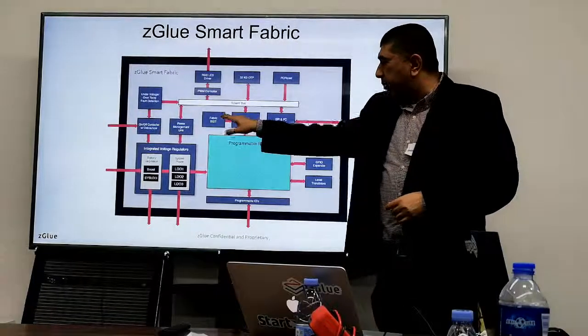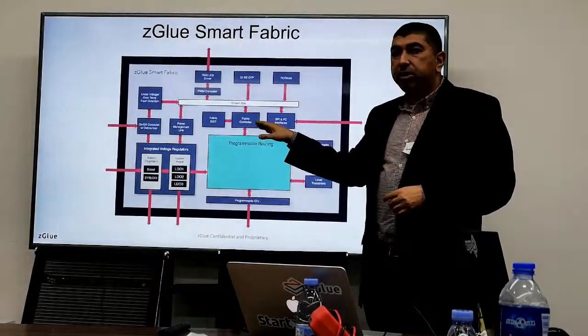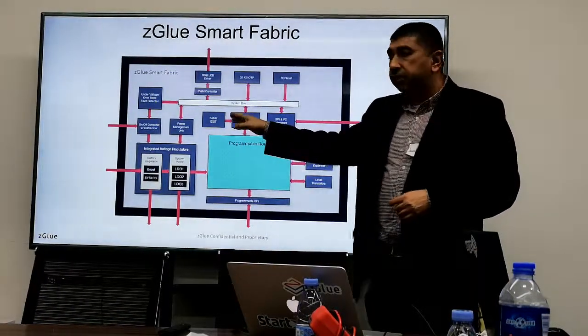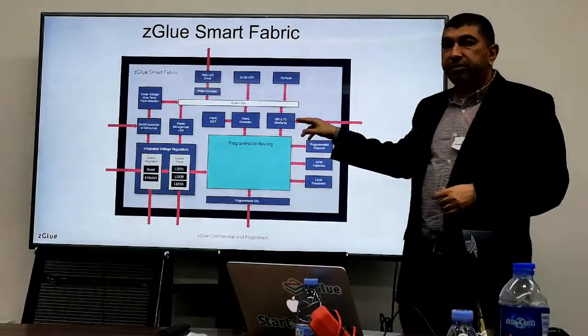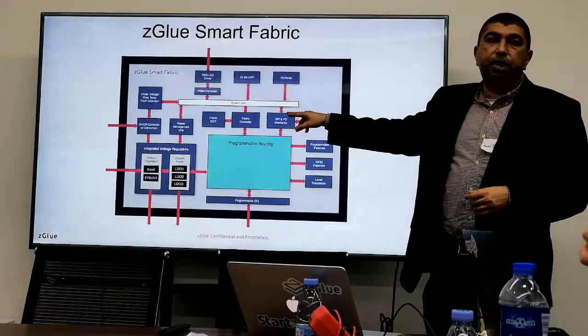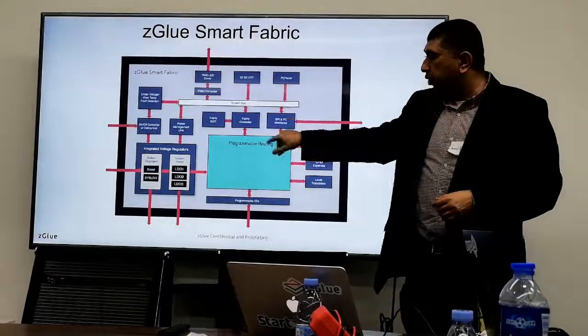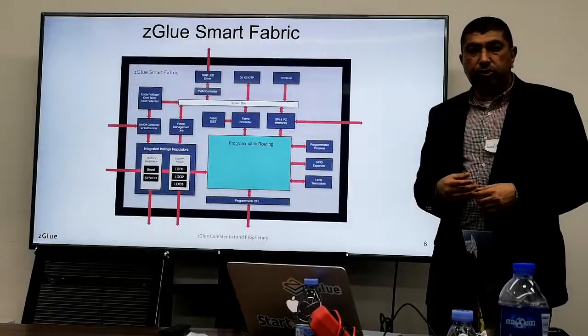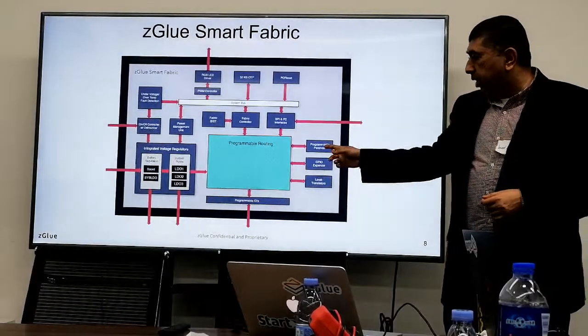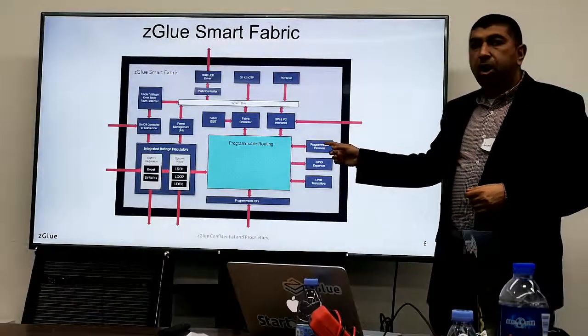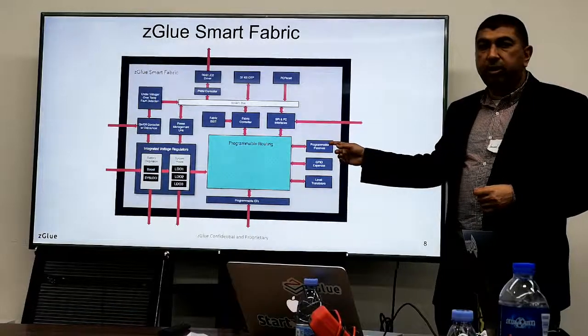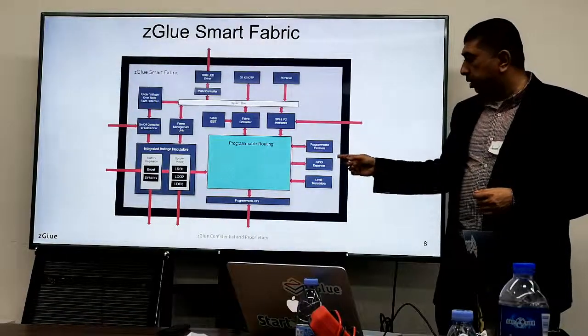If you look deeper inside, you will see a fabric controller that controls the connectivity. There is built-in self-test. You have the option to talk to this chip from outside or from the top using SPI or I2C. As we said, there are lots of programmable resistors that you can put into your schematic.